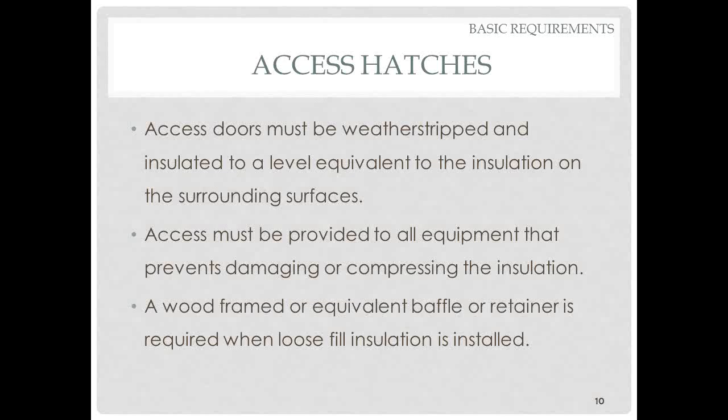There's a couple other details there. Access has to be provided to any mechanical equipment that's up in the attic, and of course in Vermont we want to minimize whatever mechanical equipment is in attics anyway, but if you put anything up there that requires maintenance, you need to create a pathway so that some service person can come and go without trashing your insulation job. Also, there needs to be a sturdy baffle around the hatch to maintain the physical integrity of the insulation detail there.